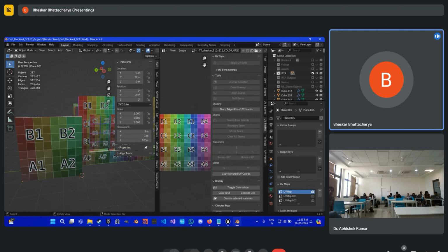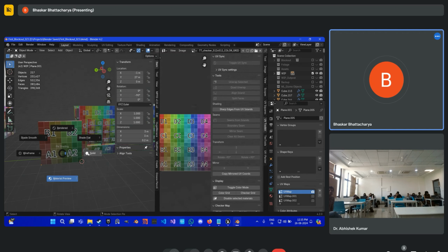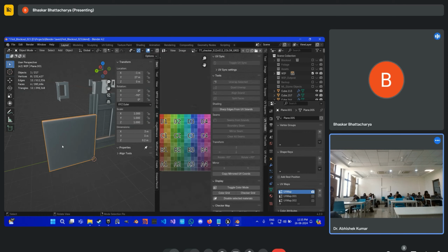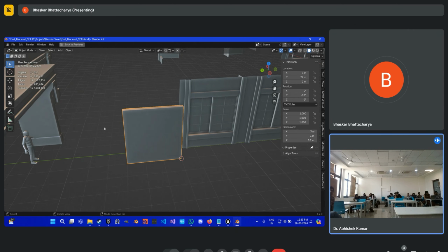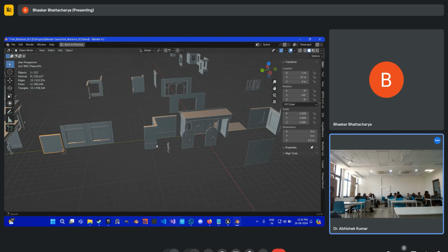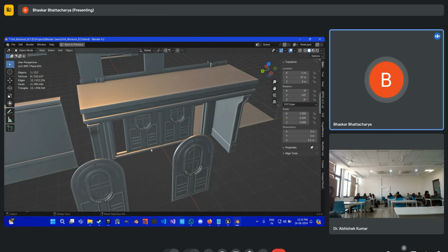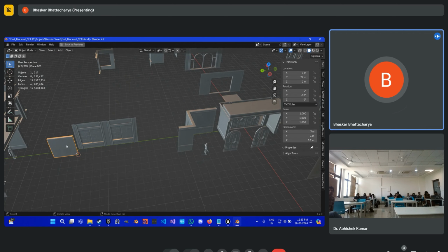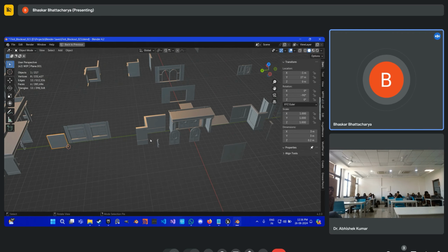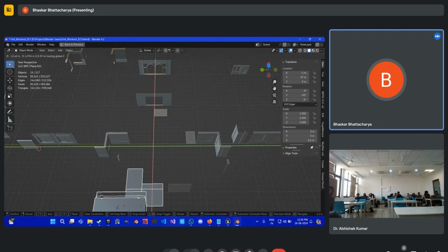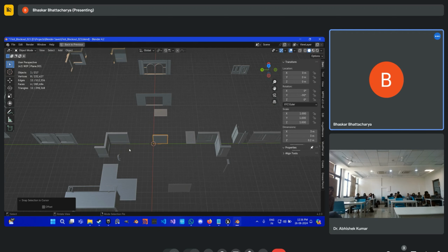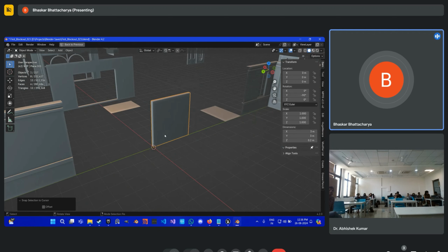For Blender, we will see the export settings that we commonly use. I'll just use this simple cube for now. One thing you should know is that Unreal treats the world origin as the origin of the object. So if your object is over here and the world origin is over here, then inside Unreal this object will be very far from its pivot, and that causes a lot of issues. So what I will do is move this around for now and set this to the world origin.